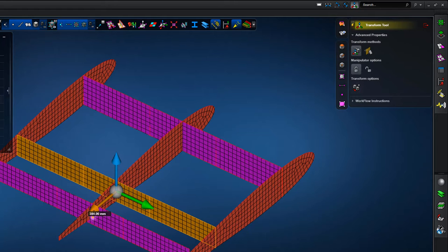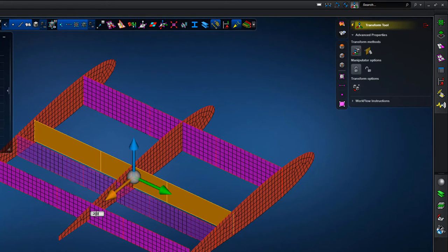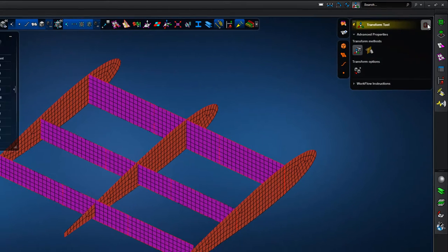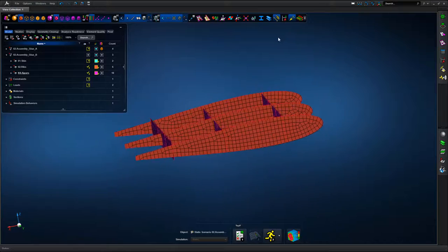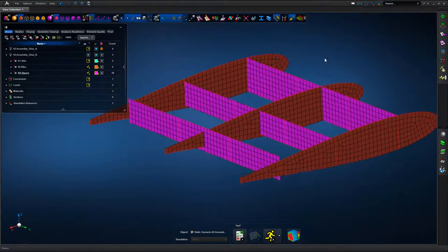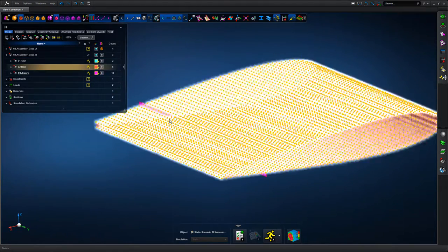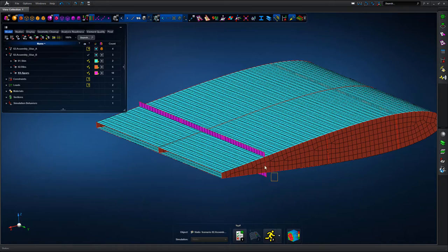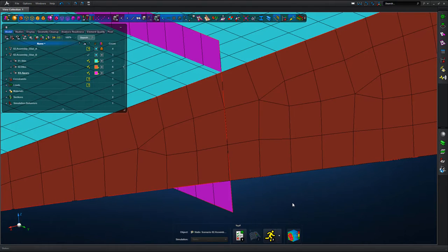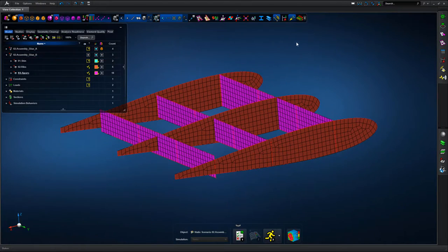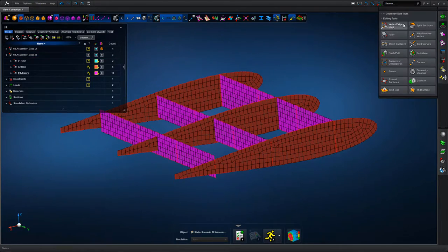So moving the rearmost spar, moving it in space, so taking a copy, and then moving the original back into the broad center of the rib. Now the problem with this is that of course we've moved the spar or the spars, and the parabolic shape on the rib means that the spars no longer fit the wing box, or they don't meet the wing skin as intended. So some very quick and simple tools using the geometry manipulation.